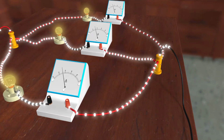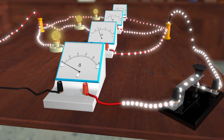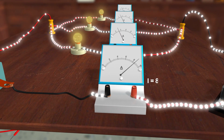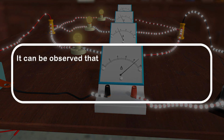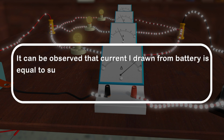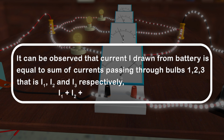Measure the current drawn from the battery using ammeter 1 connected across it and note the reading as I. I is equal to 8.8 amperes. It can be observed that current I drawn from the battery is equal to the sum of currents passing through the bulbs 1, 2 and 3, that is I1, I2 and I3 respectively. I1 plus I2 plus I3 is equal to 8.8 amperes, that is equal to I.